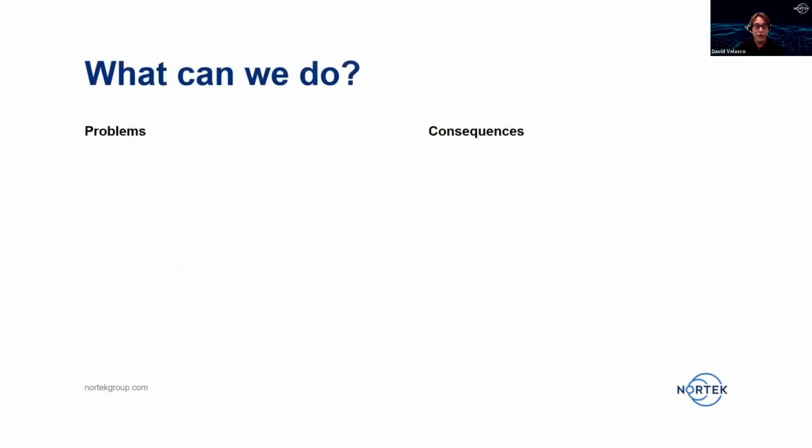So what can we do? Well, we have some problems and some consequences to deal with here, right? Now, in general, there is poor range resolution for most ADCPs. And what we mean by that is that the cell size only gets down to a certain length. So you cannot see smaller variations than the cell size.